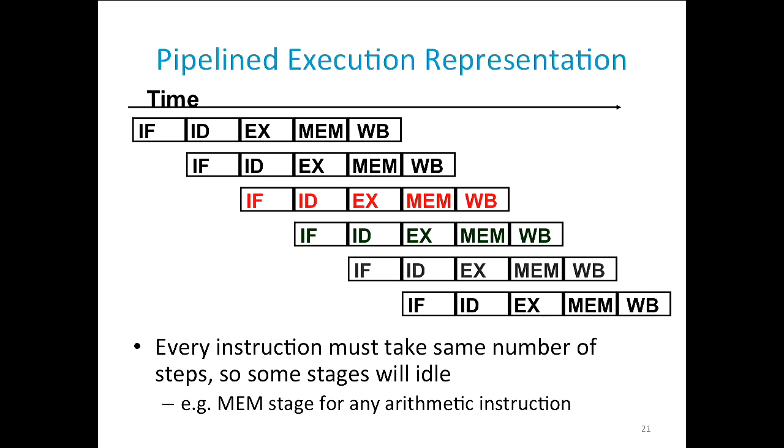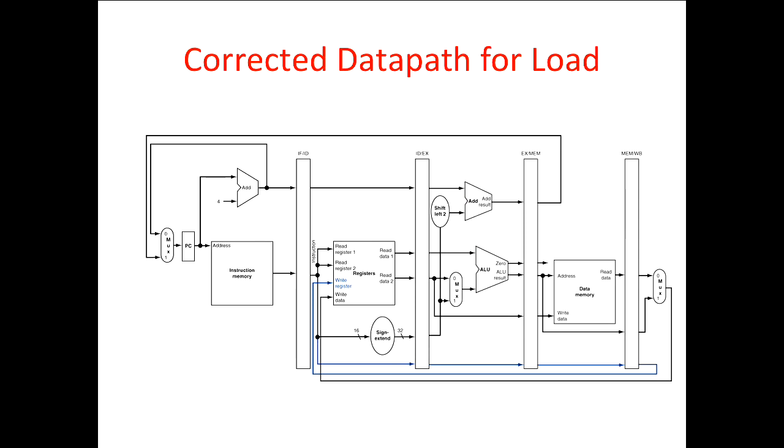Yep. So the question was, how do you keep track of the control bits? Well, you capture them here. When you fetch them from the instruction memory, they come into this register. Then I'm explicitly capturing those in more bits. More register bits are needed to carry that instruction down the pipeline along with the data as you process it, so you're keeping track of what that instruction was.